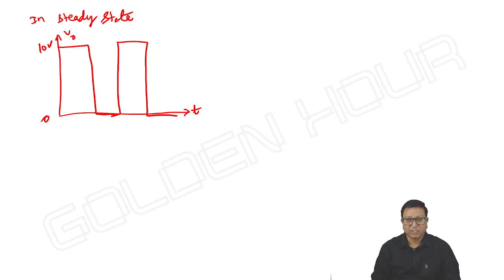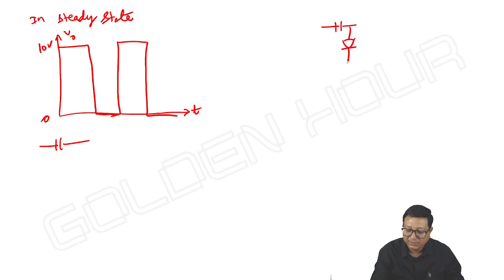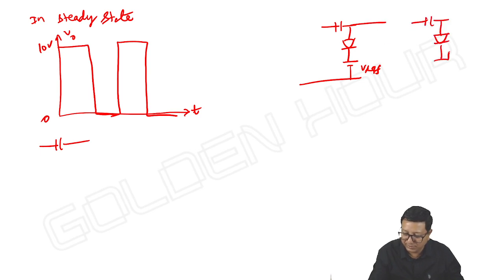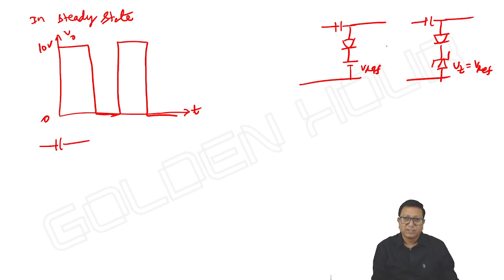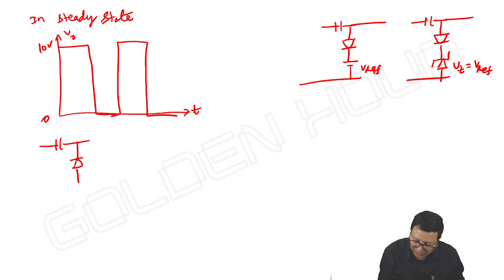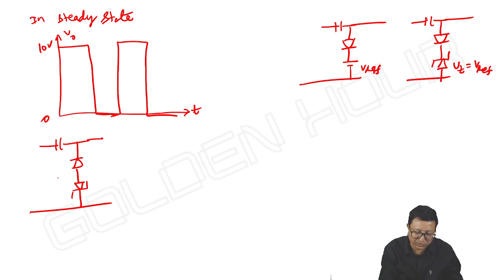Okay. Next point. If you have a reference voltage, then how do we do it? The same thing. So with the negative reference I am taking. See, in negative clamper I took this circuit, right? Some reference voltage we have. Then instead of the reference voltage, I can write here a Zener diode, where Vz is equal to V reference. Okay, it is possible. The same way, in positive clamper, I have to take a Zener diode whose direction is downwards.